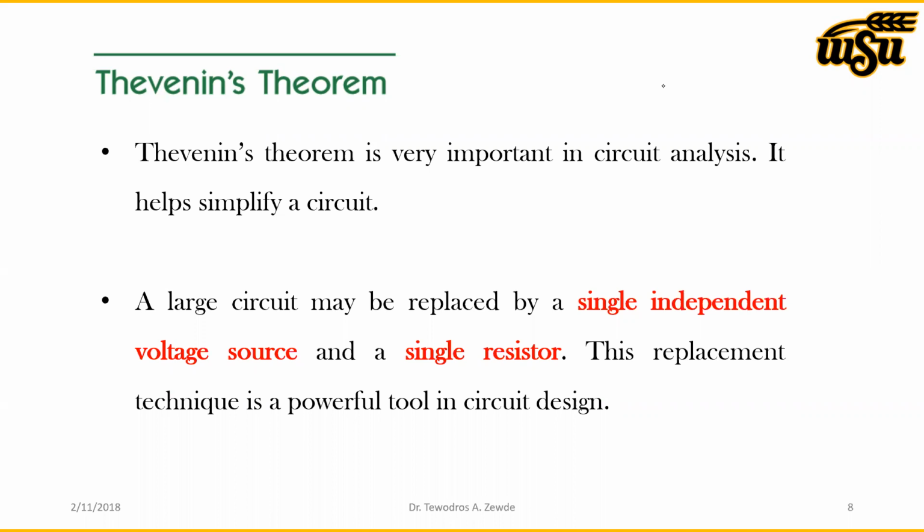When we apply Thevenin's theorem, a large or complex circuit can be replaced by a single independent voltage source and a single resistor. This is very important to simplify the circuit, and as I said earlier, to determine a voltage or current across a given device or element for different voltage and current values.